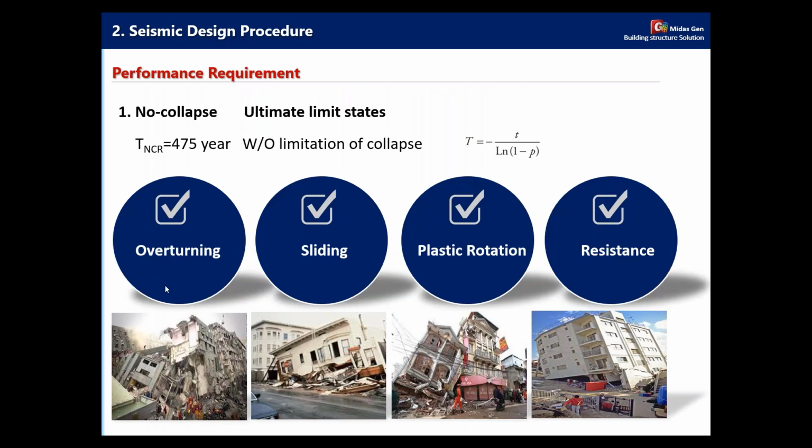For the performance requirement, when we are doing the seismic design, we need to check the overturning of the structure, sliding, plastic rotation, and the structure has to have higher resistance. You can see the reference return period we usually use in the building code when we are doing the seismic design.